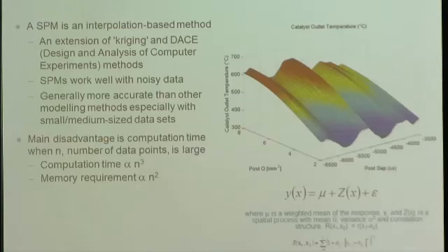The main disadvantage with SPMs is computation time, and that's because once you've got your model and you come to optimise, as I say, you're optimising at all different speeds and loads over several test cycles, and you've got multiple objectives, multiple constraints, and a prediction function that's relatively slow is a bit of a hindrance.